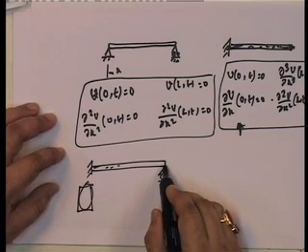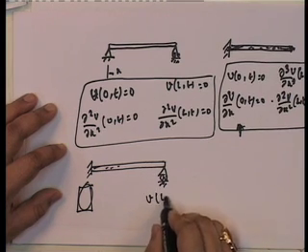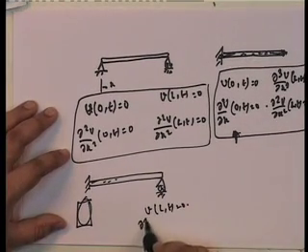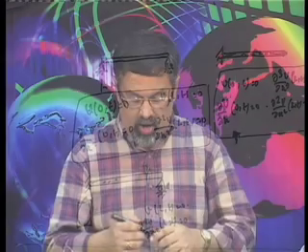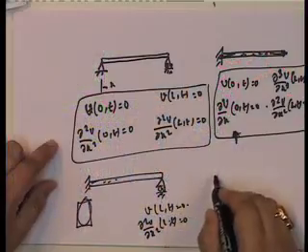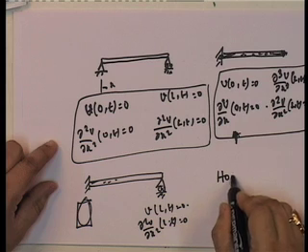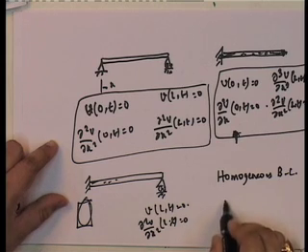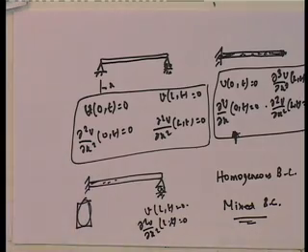Well, you can't say anything about shear, but you can definitely say the displacement. So v at L of t is equal to 0, and what else? You know that the moment is 0. So you know ∂²v/∂x² at (L,t) is equal to 0. So this is the way. Of course, these are known as homogeneous boundary conditions. We might have mixed boundary conditions too. I will talk about those later.